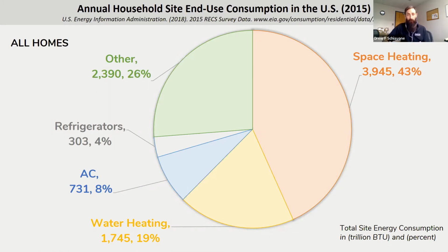And so that's the importance of keeping that heat where it should be, because if you weatherize your house and seal the air leaks, so you're keeping that heat where it should be, then your heating and cooling systems will be more efficient. They can be designed smaller. If you're replacing a heating system, you might be able to size it a little bit smaller and save some money that way as well.